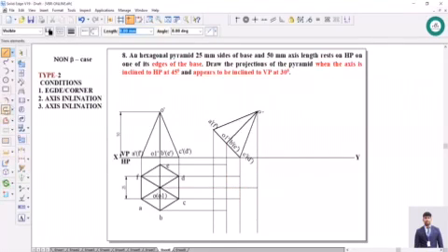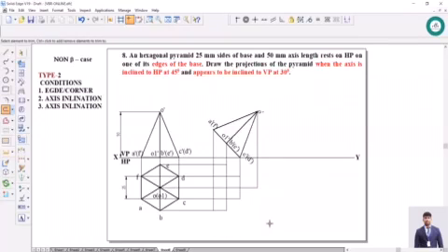Next, go to trim, trim this extra part, go to move option, switch on the copy, and just copy the namings here. Instead of copying, you can also use the command text, and you can just text here. Since it is already readily done, you can just copy this.